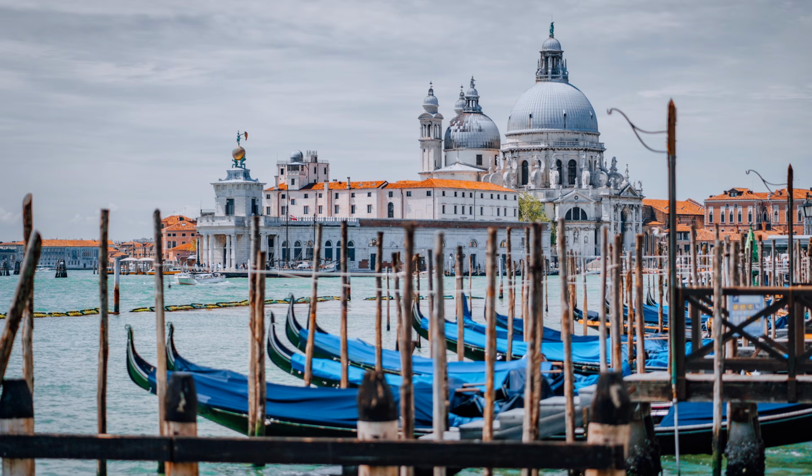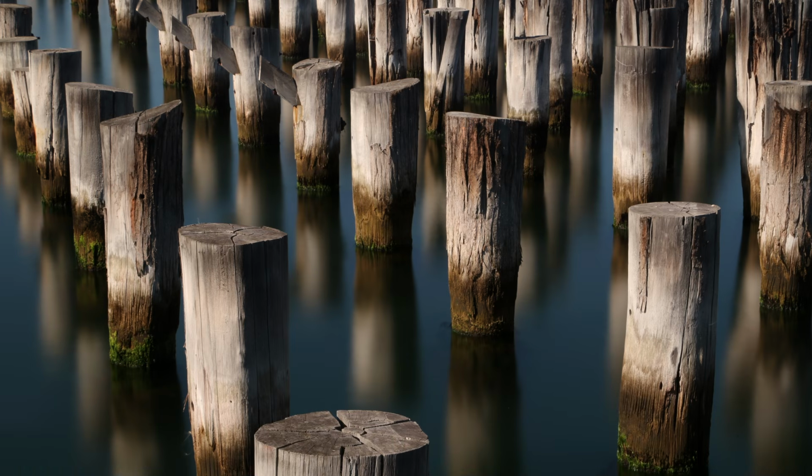If you take, for example, a ship's hull, or if you think about some of the timber that is completely submerged underwater, like in Venice, you've got various structures that are built on it. You'll notice that within those, they haven't rotted. The place where you start to see some of the decay and the rot are the places that are wet then dry, or persistently wetted, but still have access to oxygen. So just above the waterline on a timber ship's hull is where you get some of the decay happening. But you don't get it below the waterline. That lasts a huge amount of time.